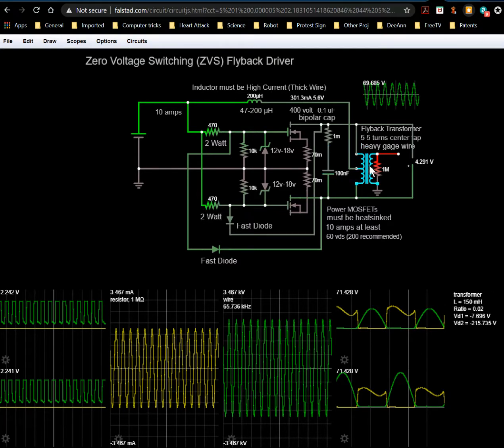But inductors, you can't do that, because you have to maintain that magnetic field, and as long as you've got that current flowing, you've got a magnetic field and energy stored in it. But once you try to remove that, this thing freaks out, and it will generate whatever voltage it can across its terminals, and it's going to be reversed too, by the way.